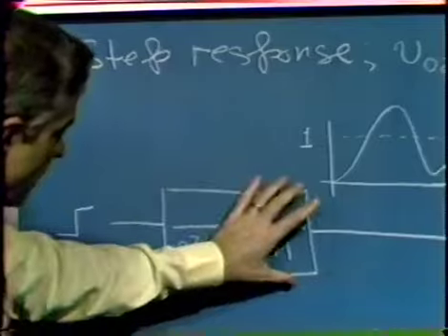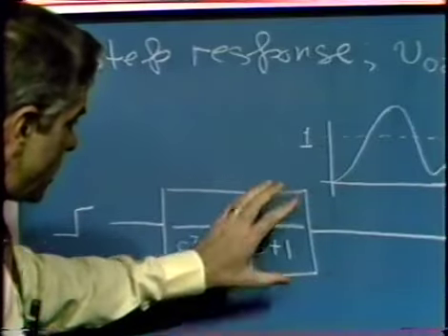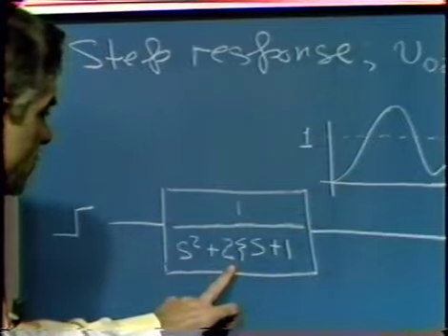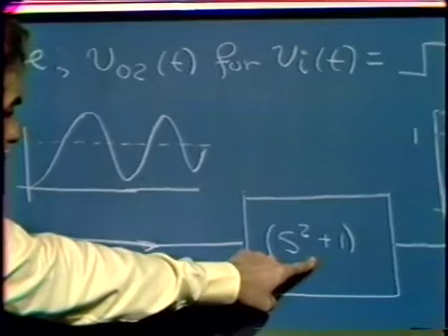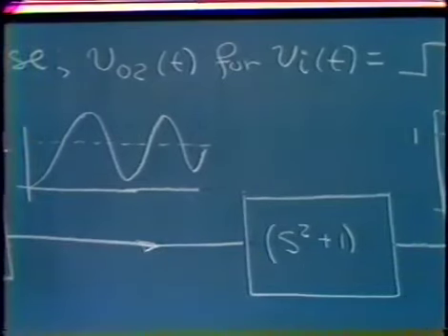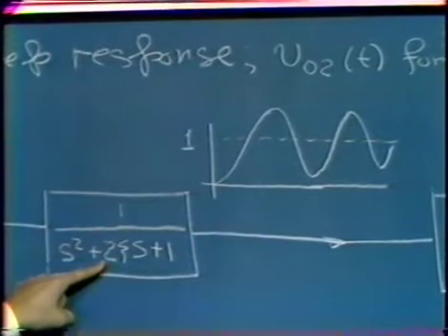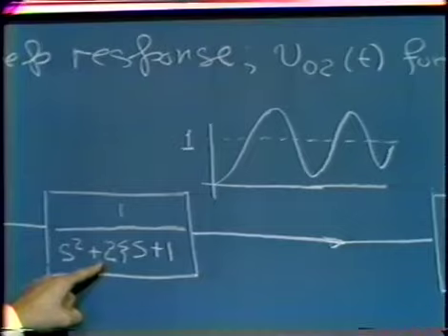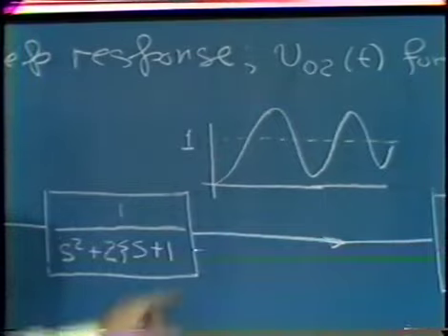And I'll factor the system so that we have a block in the block diagram that gives us the complex conjugate pole pair, and then we'll follow that with the complex conjugate pair of zeros. Let's put a step into this box. We've looked at the step response of a lightly damped complex conjugate pole pair several times before. It has this general form. That was a response we looked at several times ago.